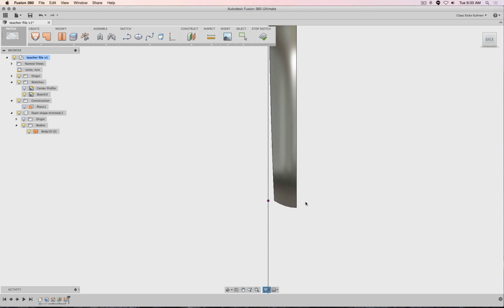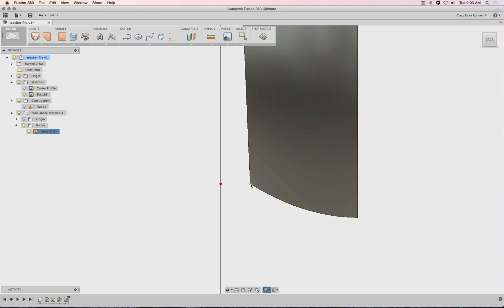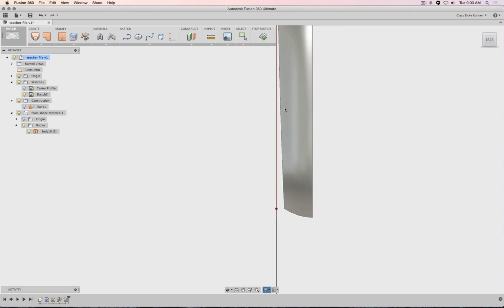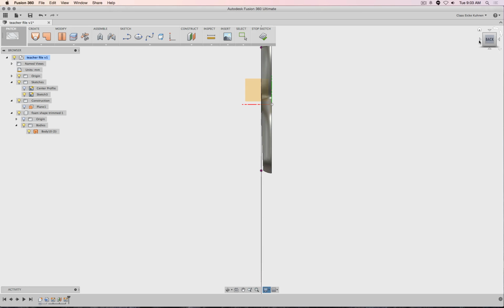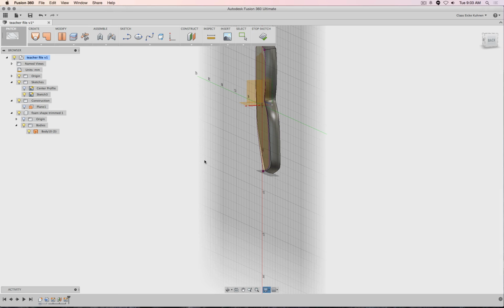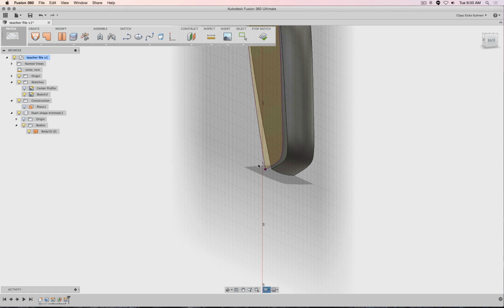So like a projector, the geometry is in a parallel way projected onto my sketch plane. But there's also another problem. You see this point simply got moved perpendicular to the sketch plane, but the surface kind of arcs. So if later I want to cut something, I need to have a sketch here so I could create this nice arc. So this approach also doesn't work. Okay, no problem. So what else can we do?